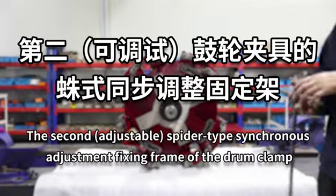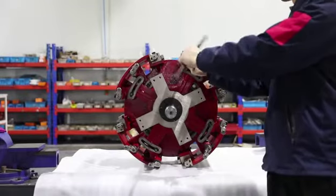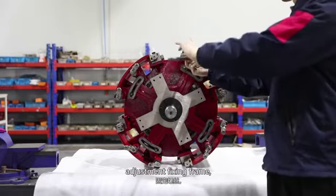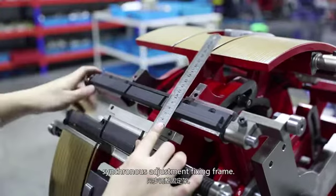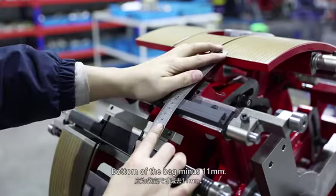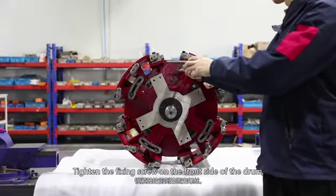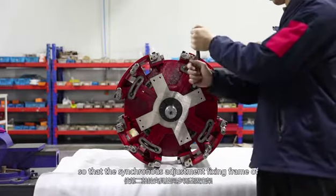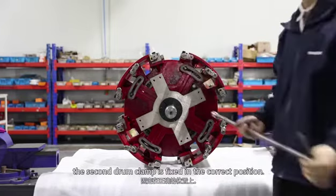The second drum clamp synchronous adjustment fixing frame. Loosen the fixing screw of the second clamp's synchronous adjustment fixing frame and turn the second drum clamp's synchronous adjustment fixing frame. The correct distance should be the size of the bottom of the bag minus 11 mm. Tighten the fixing screw on the front side of the drum so that the synchronous adjustment fixing frame of the second drum clamp is fixed in the correct position.